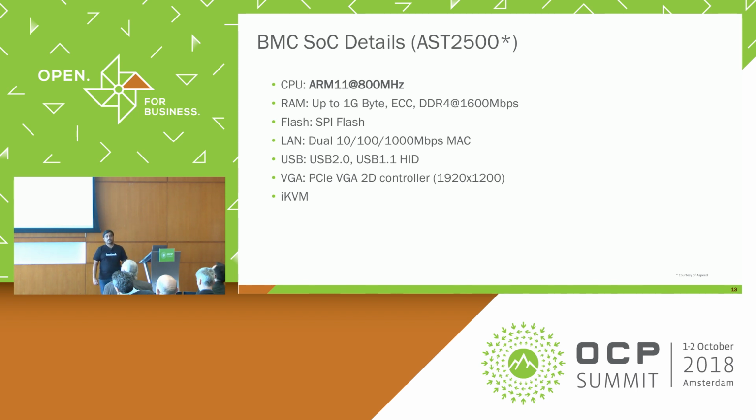And this was not new, as I said before. It has been there for 20 years. But what has happened with recent technologies, with inexpensive silicon, is that BMCs have become more powerful. Back in the day, it used to be a simple 8-bit microcontroller, like a Renesas H8 kind of thing. That used to be the BMC. And all the code running on it was pretty bare metal. Sometimes assembly, sometimes bare metal C code. Then in the last decade, the BMCs became more powerful, like 16-bit microcontrollers. Now we added FreeRTOS or VxWorks as the operating system, and we do much better manageability.